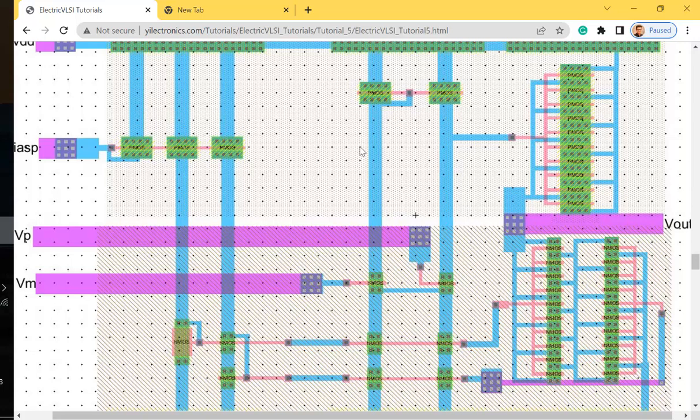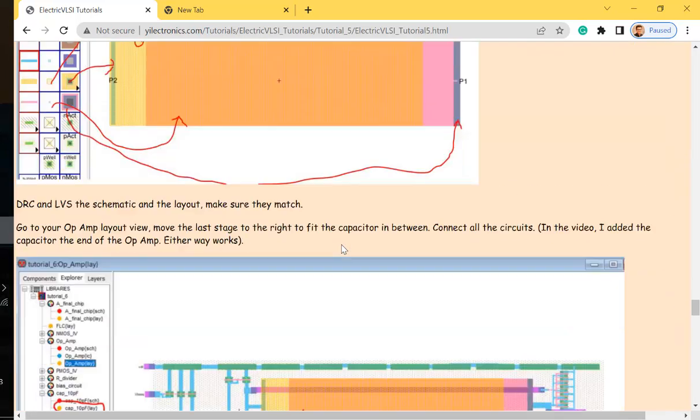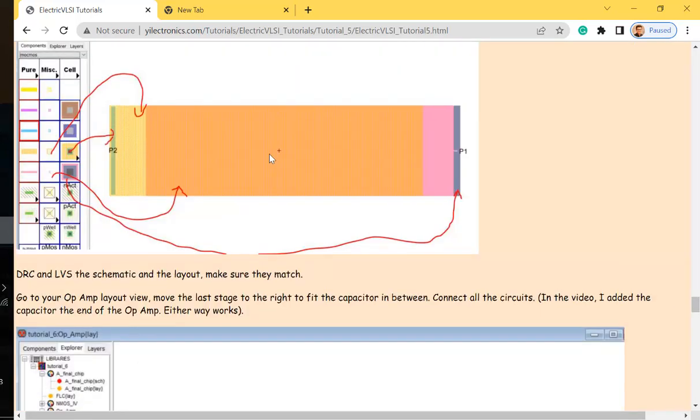and these are just metal wires. This is metal 1, metal 2, and the yellow ones are metal 3. And then eventually you design a capacitor in the chip. Could you believe that? There are just 2 polysilicon layers on top of each other with overlap, so you've got a dielectric material in the middle. You've got 2 plates that form a cap. You can only modify the area of the cap to change the capacitance.